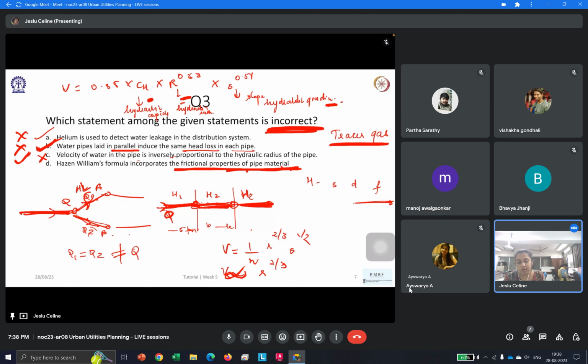To an extent, okay, maybe, but the main one comes in this 0.85. This one is actually calculated. For the hydraulic capacity, yes, to an extent you can say it is different for different pipes. We are solving it in that way also, but by default we do not do any calculation or say that for this particular case we are taking this one. So maybe a combination, but actually it comes in this 0.85, where we got this factor by calculating a hydraulic radius of 1 feet and a frictional slope of 1 is to 1000. So for this frictional slope, we have got 0.85.